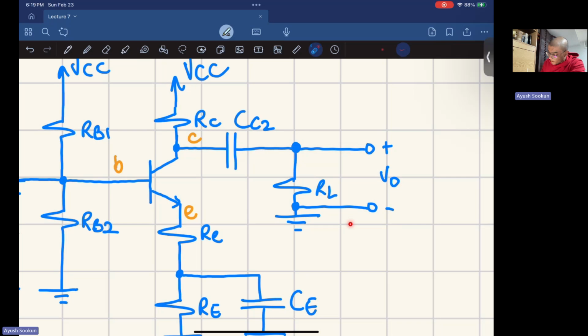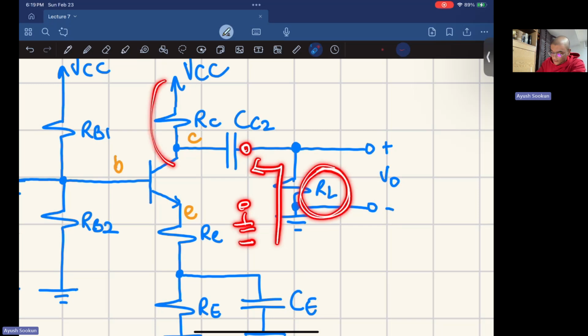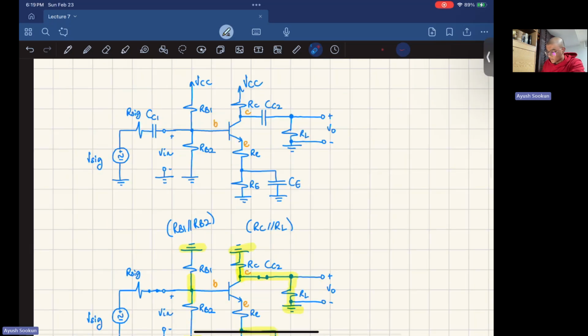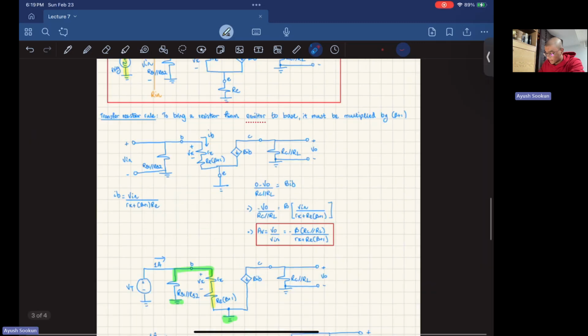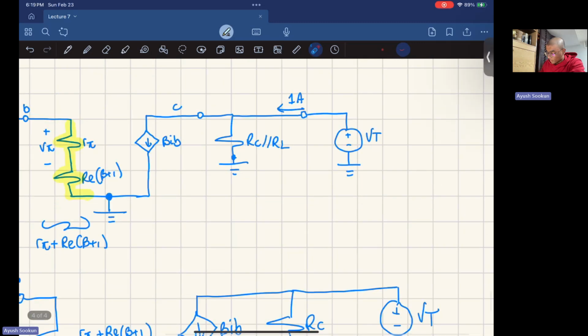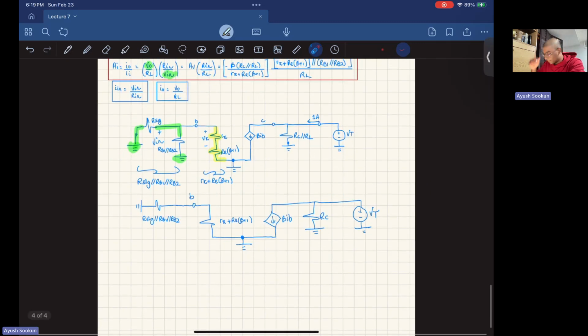And also, when you're doing output resistance, it's going to be pointing to the output voltage right here, which is not considered RL. It considers RC because we haven't done the combination in the initial circuit. That's how it was given to us. It was just told that the output is taken at RL. We have no choice over that. So we have to make sure that when we're copy pasting our circuits, we're being very careful not to consider the RL as well.